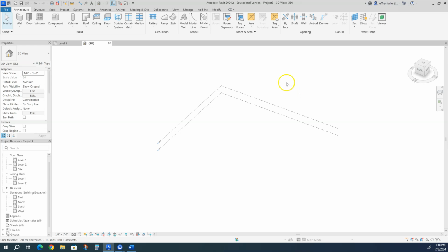You can press that button in, and then press the shift key, and then you get orbit just like this, just by moving your mouse around. If you release that and then just push on the center button of the mouse, then you get the panning effect.